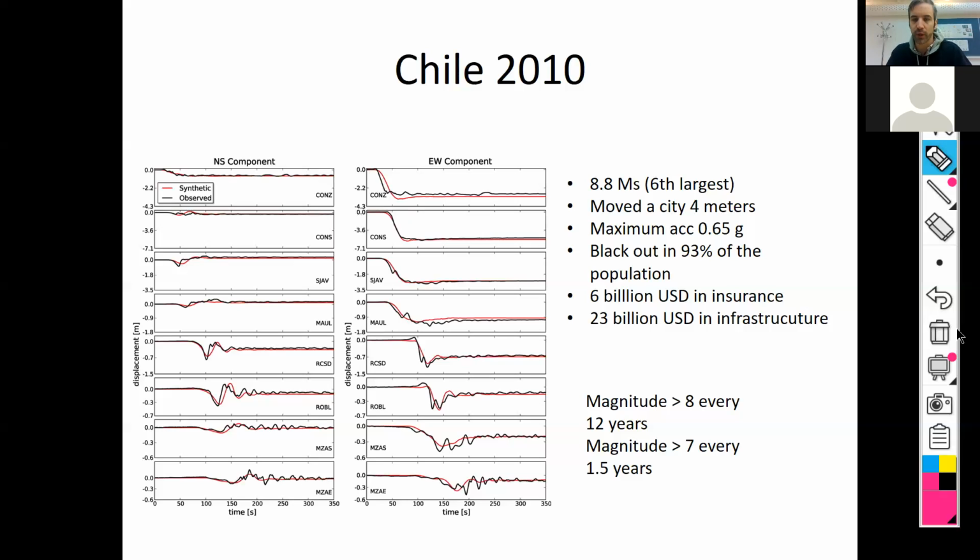So of course, if you have a building and you design each column to support the weight of the structure, and maybe a couple of meganewtons, it's not unusual for a column to support a couple of meganewtons, then the column should be designed to support 60% of that mass or over that force in a sideways direction.